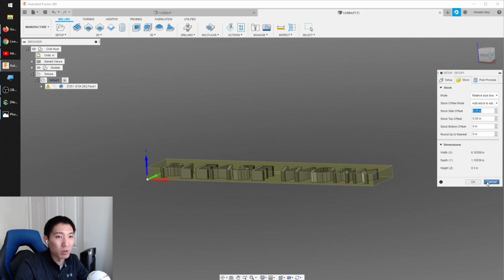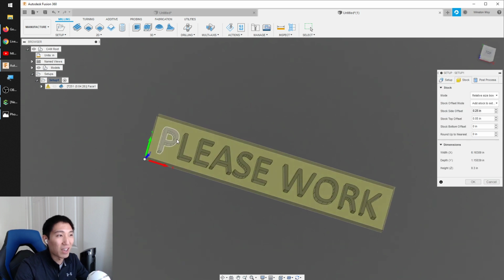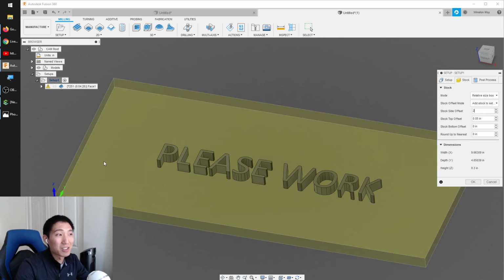And that's more important in 3D machining operations, because Fusion will machine anywhere it thinks there's stock that's not your model. And unless you constrain it to work in a very specific area, it's going to try and machine everything away. So if I were to say my stock is massive, it's going to try and machine everything away. But for a 2D operation, we can say, just follow these letters. It's really not that big a deal.